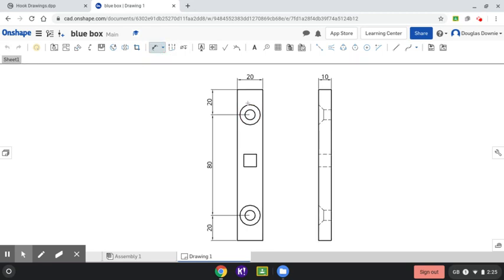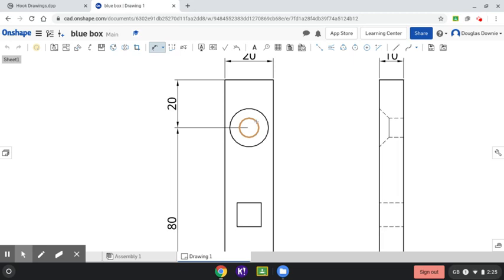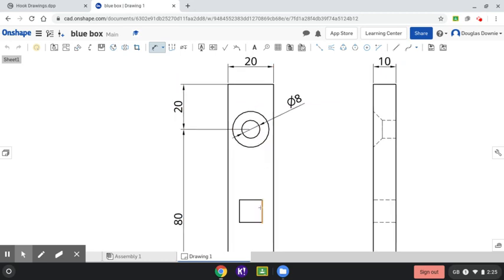We'll maybe need to zoom in a little bit here. Make sure we get the right hole. So we're looking to get the middle hole, the smallest of the circles. Now always try and drag out the dimension line so it's not crossing over like that. That's bad practice. Bring it out to about here and then click. And we're also going to do the same with this line here. Remember that's a 10. Again, try and make sure you get the 10 in the centre and click.